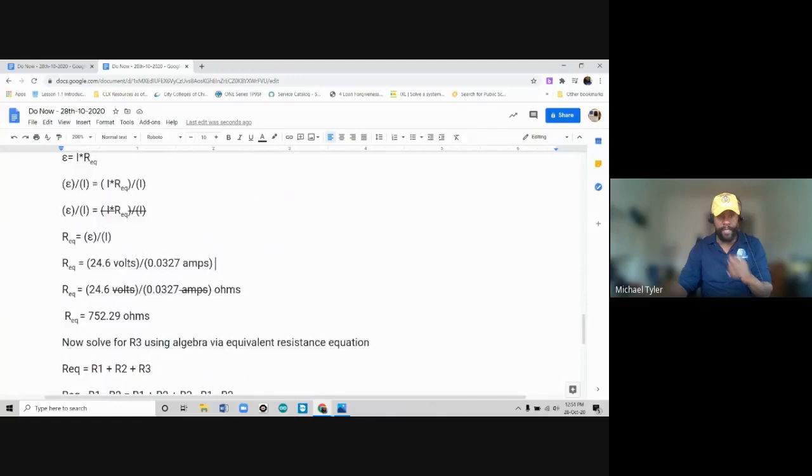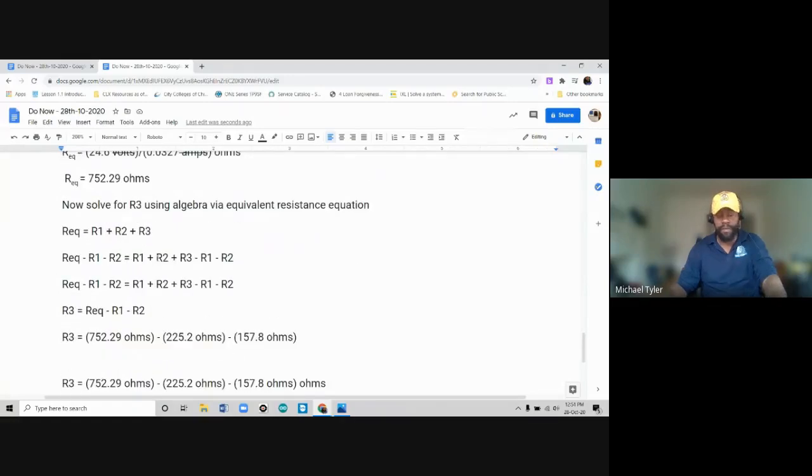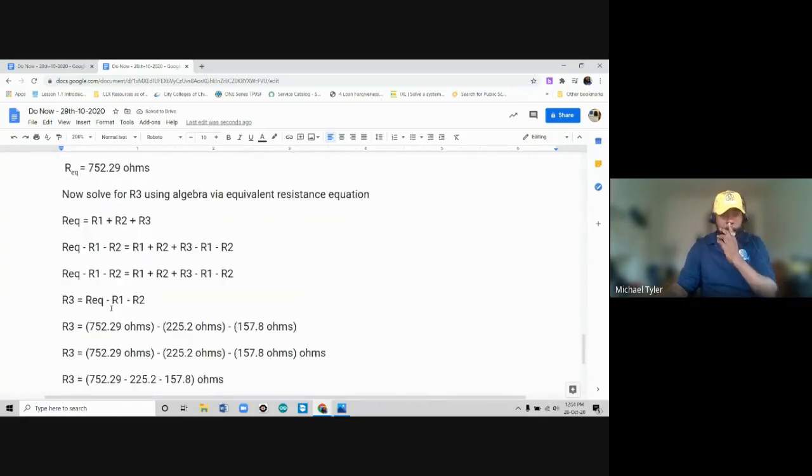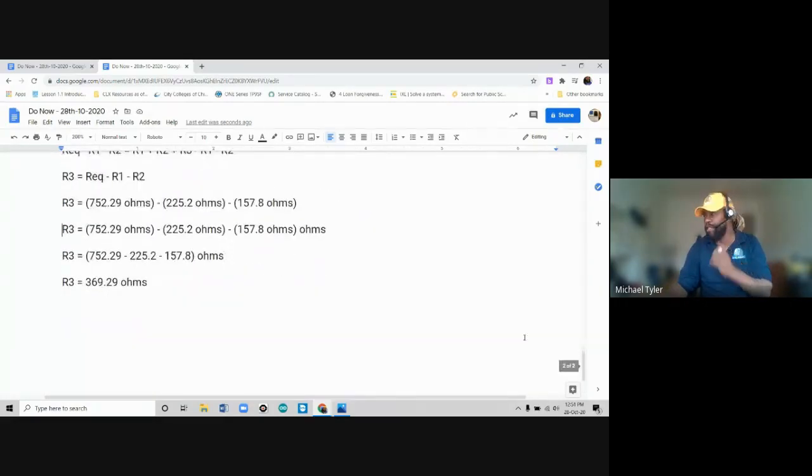That looks extremely clean. All right, now we got to fix all this other stuff. This is REQ subscript. This is R1 subscript. All that has to change, everybody, okay? And then you continue on with the notes. And the next part is the voltage values, because we found out R3 here. So what I was saying in this step is ohms crosses out.